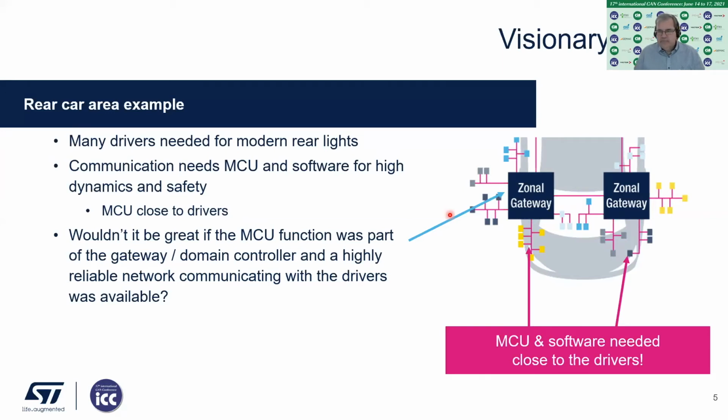And for these quite appealing lights, we need many individual light sources. And when I talk about many individual light sources, I talk about several hundred, 600 and above individual light sources that need to be dynamically animated. So for that, we need many drivers here in the rear light. And for communicating with these drivers that drive these rear light LEDs, we usually need a microcontroller and the software for this high dynamics and safety very close to these drivers.